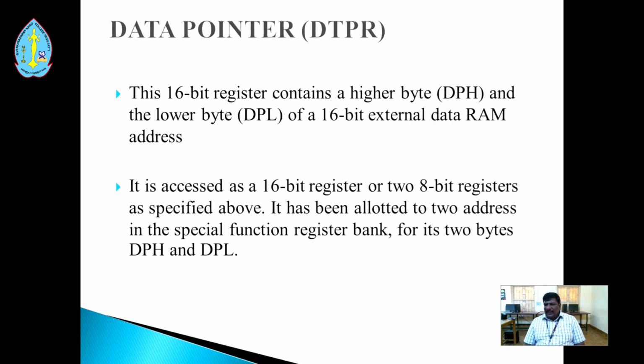It holds the external data RAM address. As already said, it is accessed as two 8-bit registers. It can be allotted two addresses, one for each of the 2 bytes. It needs 2 bytes, called DPH and DPL.